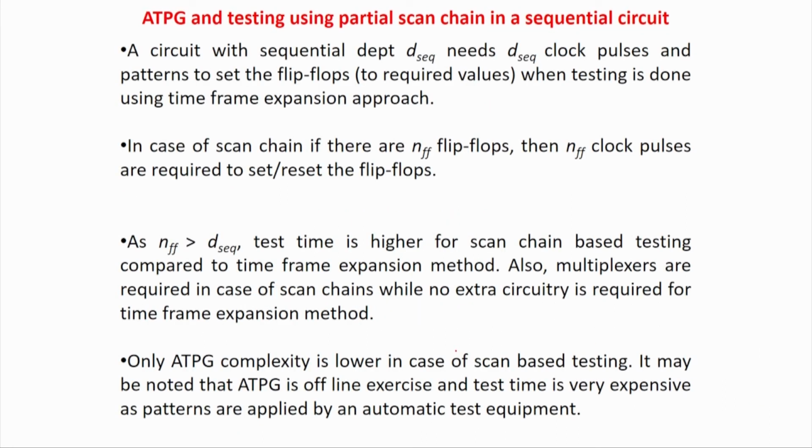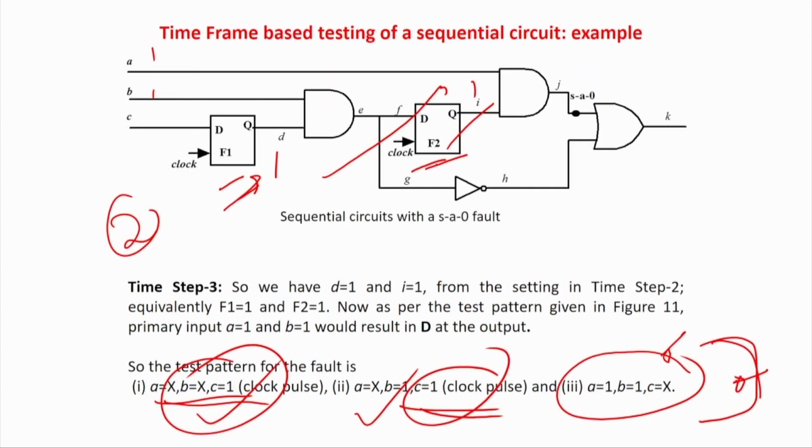So some of the flip-flops which are very far down the line in depth, I will put scan on those. But some of the flip-flops which are very easy, like this one, I really do not require any computation. It's a primary input directly connected. To get a 1, I just require a 1. So ATPG to find out how I can get a 1 is very, very straightforward, and will not take much time.